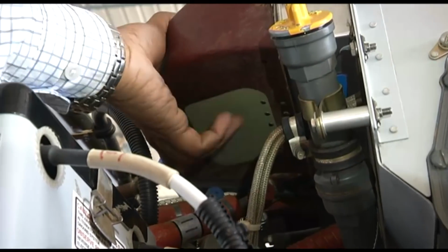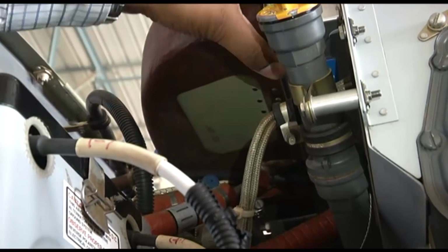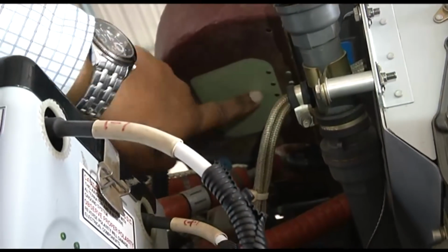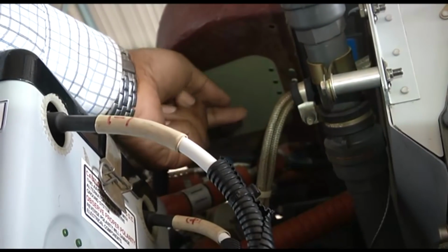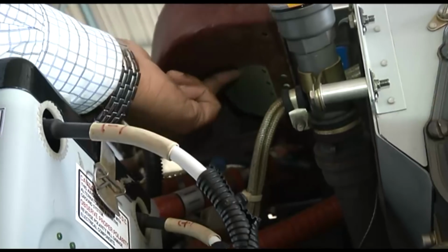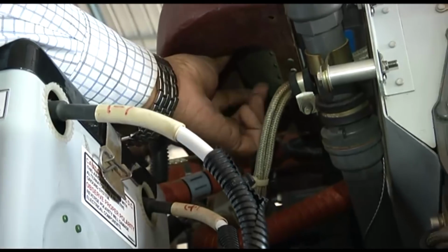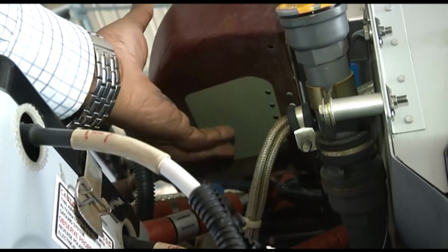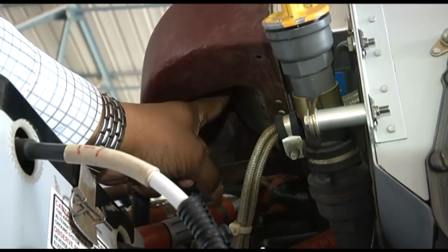Here you can see, just at the bottom of the duct, just outside the induction air filter, there is an opening. This is called the alternate air opening. As we have seen in our slides, in case the filter gets clogged, then due to the engine suction, this opening gets open and alternate air goes through this opening to the fuel air control unit. So we have seen the induction air filter, the duct and the alternate air entrance.